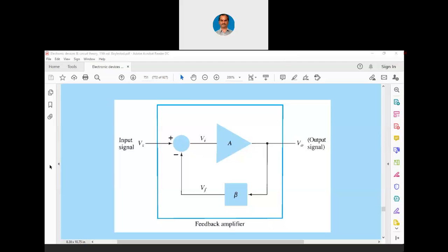It is called a buffer because even in digital circuits, digital signals will have loss when they pass through wires. Whenever there is a loss of digital signal, it passes through a buffer so that the signal's original amplitude is reconstructed. So even in digital circuits we use this symbol, but there it is not an amplifier; it is a buffer with a gain of unity, meaning whatever the input signal is, that is produced at the output. It is basically a digital signal there, and there is no inversion at all. The signal goes as it is.